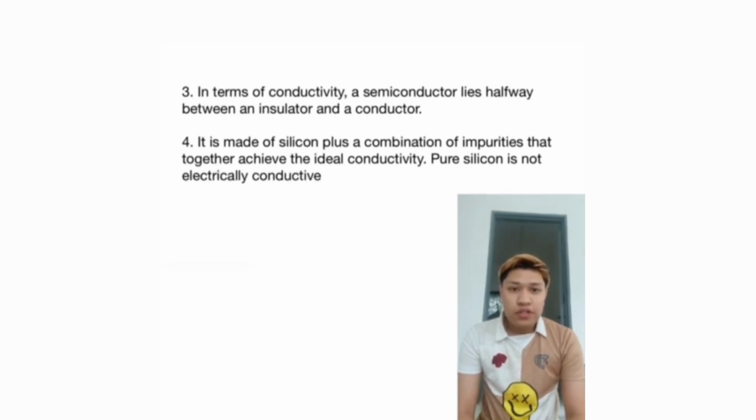We move on to the function of CMOS. Your laptop BIOS firmware, which is in charge of starting up your computer and configuring data flow, is powered by the CMOS battery. If your laptop has trouble starting up, if drivers disappear, or if the date and time on your laptop are off, your CMOS battery may have died.